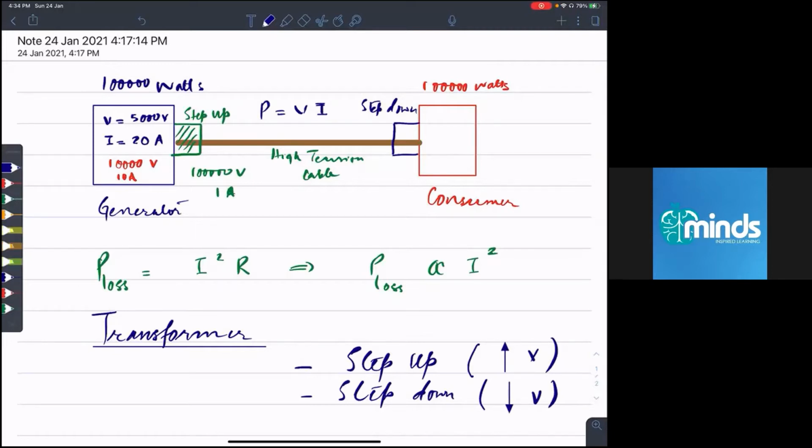That's why that fast charging is known as adaptive fast charging, because that charger recognizes the device and then it decides what potential difference it needs to provide, whether it is 5 volt or 9 volt. So it means that these chargers have multiple step down transformers inside them, which transform 240 volt to 5 volt, 9 volt, 12 volt, to the lower values that we actually need.